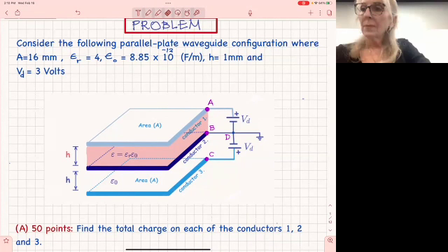And then what do they do? Silicon is low resistivity. When we say low resistivity silicon, it means you have losses in there from impurities and other things. There is high resistivity silicon also for high frequencies, but low resistivity silicon is what people are using for all the CMOS-based applications. So you're not going to use silicon to create a capacitor.